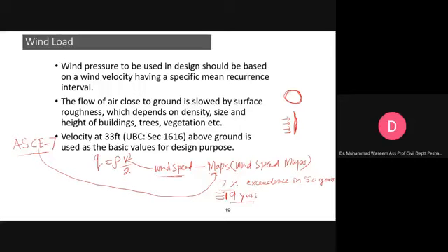You should use that wind velocity for design of your building. These maps correspond to velocities which are measured at a height of 30 feet.